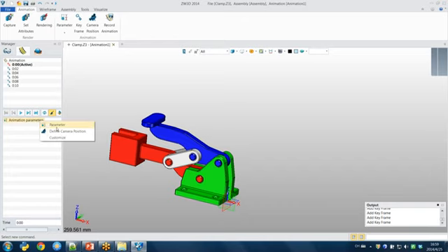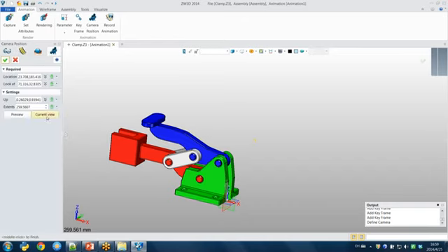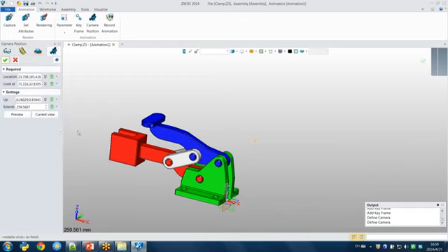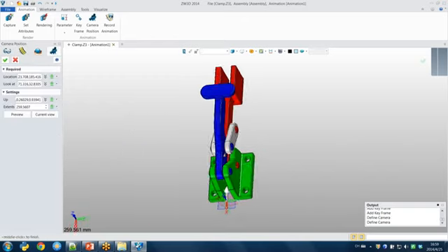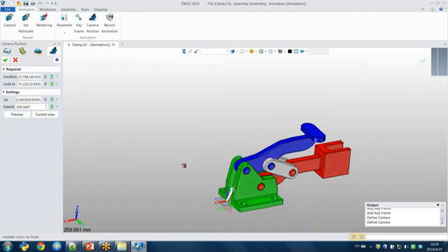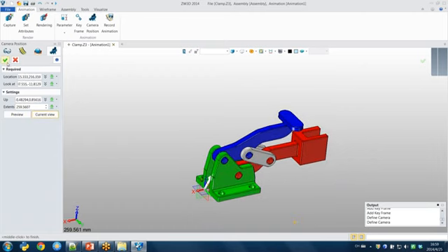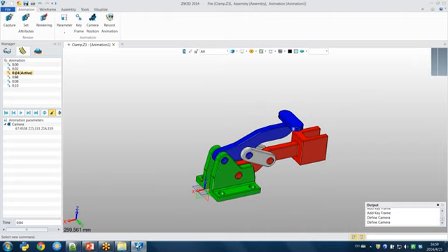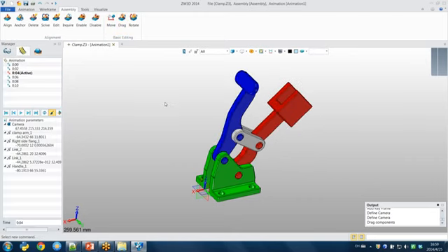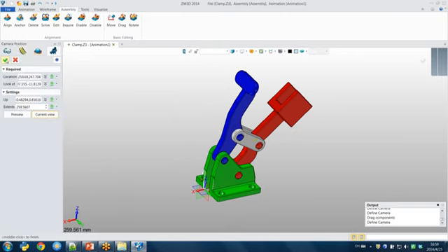So then I need to right click to define the camera position. Choose the current view. Press OK. Then I activate the second frame. I right click, define the position. I change the position. Okay, maybe just change to another side. Okay, set the current view. Press OK. For the next frame, I want to check. Okay, and right click, define the camera position, current view. Press OK.